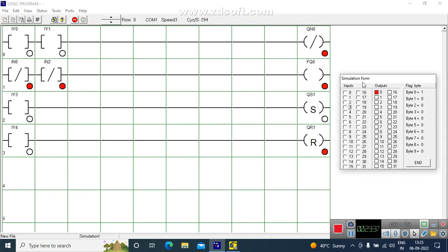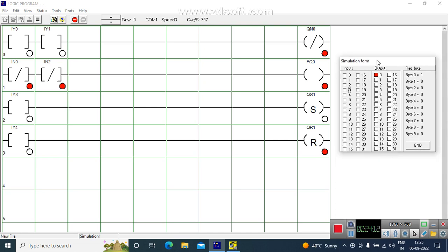Okay, as I told you, the reset flag always has priority. Priority means it has to be always on, and power is applied to any logic. The advantage of that is, when some of the programs are on, some of the programs are off, and you energize the panel, a reset pulse is given to all the reset flags, so then they get reset. So the program now can function normally.